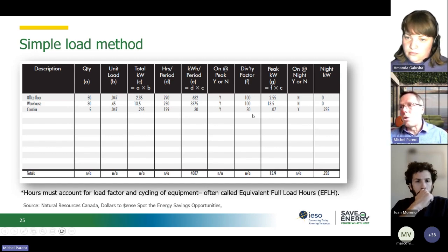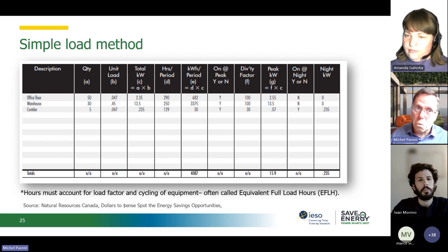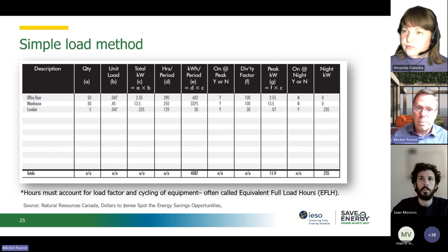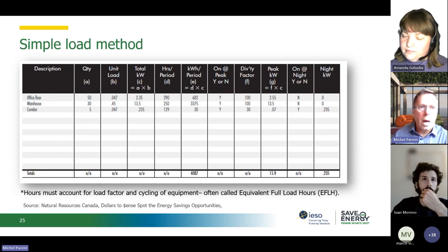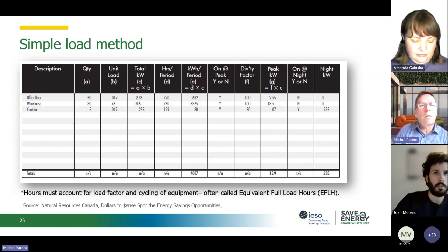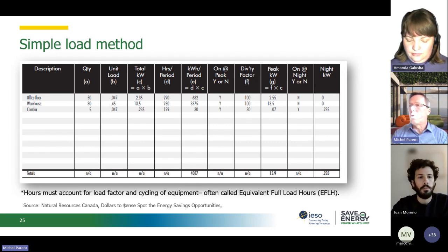Once you've got that, then you will define the operating period. And for lighting, it's just straight hours. That's pretty simple, but sometimes it is where we make the biggest mistake. The wattage, once you've got, you take care about the load and about, is there a ballast? Is there anything else that can modify that wattage? Where your biggest error will be is on the hours. And sometimes it's difficult to assess the hours. So you've got to spend some time trying to do the best assessment possible of those hours. That's why I said talk to people when you do your information gathering.